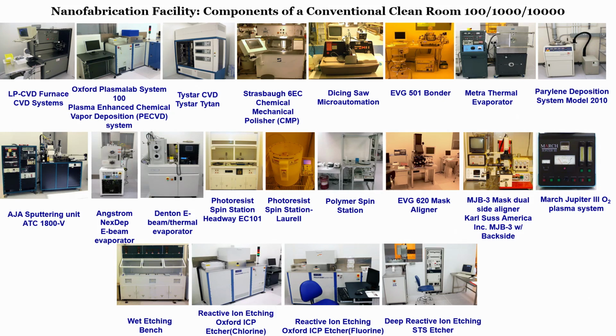One is a single sided polished wafer and one is a double sided polished wafer. On a polished wafer which is single sided, if the second side is rough and I want to polish it and make it as smooth as the front side, I have to use a chemical mechanical polisher. And like I said, once I show you the silicon wafer, you will understand more about how the CMP machine can be used. Next one you can see is a dicing saw.